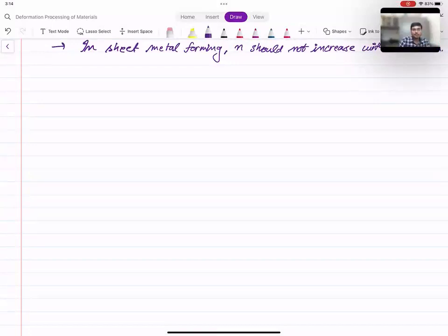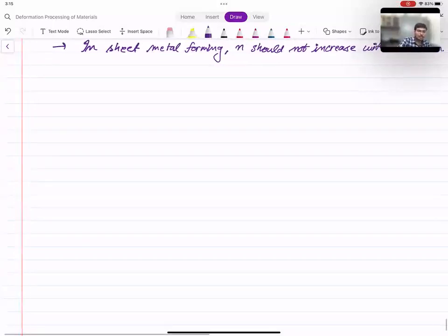In case of rolling, when the roughness parameter is low or during cold rolling, the surface finish is very good, and in case of hot rolling when roughness parameter is high, the surface finish is hampered. But that is not related to drawing, so let us move to the next parameter related to drawing operation.